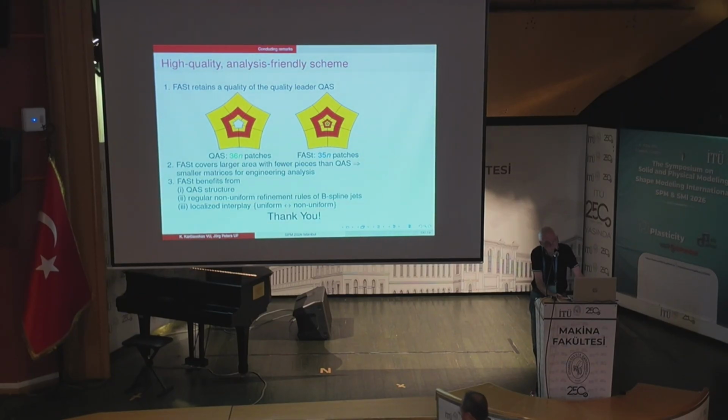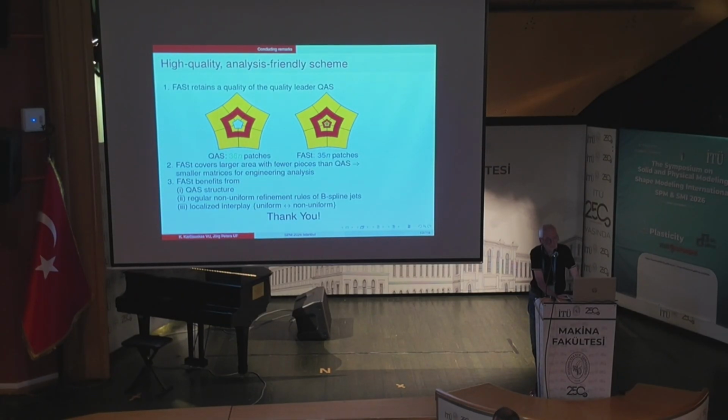Another point is that subdivision surfaces, with a sufficient amount of rings, are very convenient for isogeometric analysis. Finite schemes we have also constructed, G2 refinable, but they are considerably more complicated. That's the point.